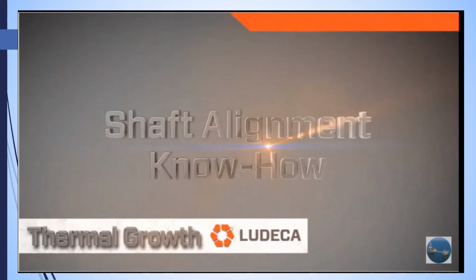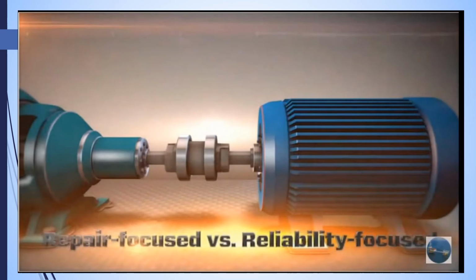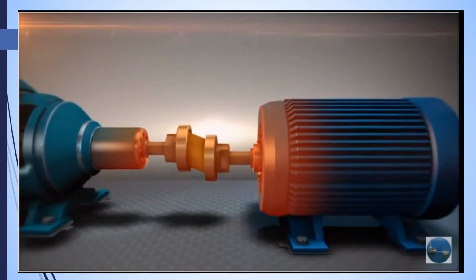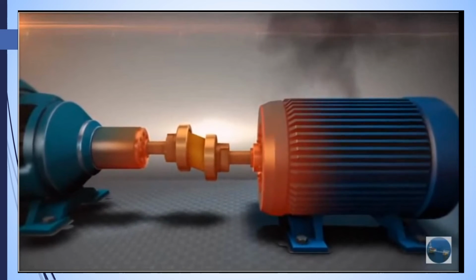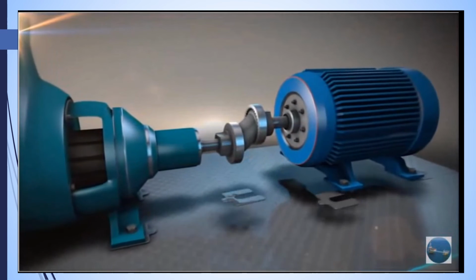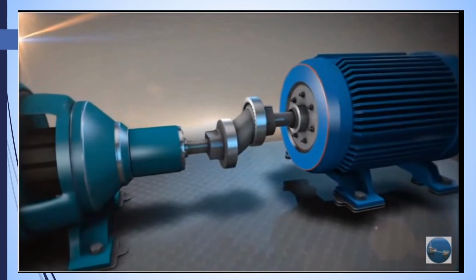Shaft alignment know-how. Thermal growth. Positional change. Not accounting for positional change in rotating machinery is a big reason why maintenance departments stay reactive instead of proactive. When rotating equipment runs, it heats up and undergoes positional changes. This can occur due to thermal growth, dynamic load shifts, pipe stress, and other factors. Therefore, it may be desirable to deliberately misalign the two shaft center lines when cold and stopped by the correct amount to compensate for these anticipated changes.